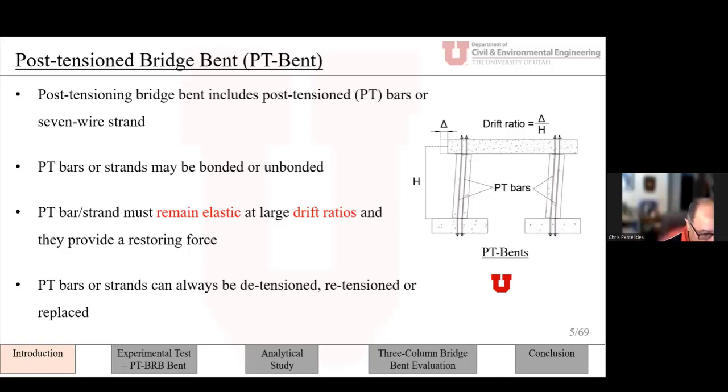And of course, the idea is that these bars are providing the self-centering that's required after an earthquake, so that if there is a strong earthquake, the bridge will come back to the original position after the earthquake. That's making it serviceable. People can drive over it, especially after an earthquake when they're trying to get to a hospital or some place like that. So it's a very advantageous system. And of course, that makes the bridge resilient, and it has very good results.